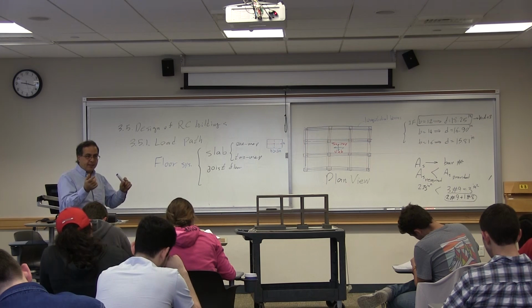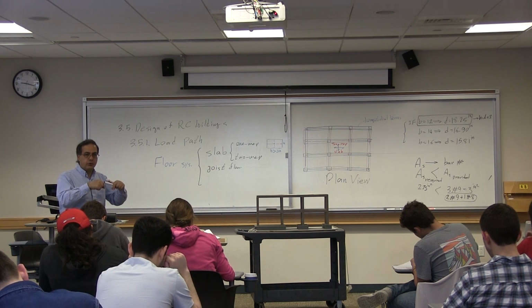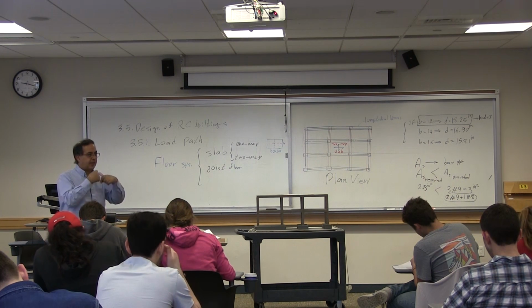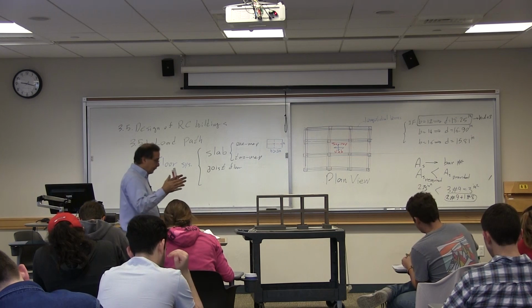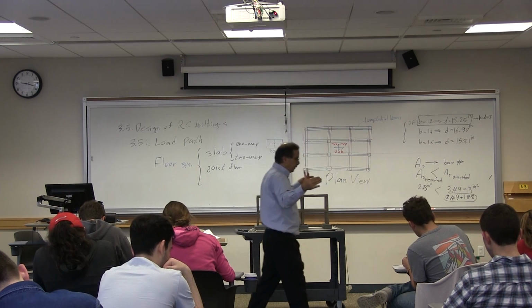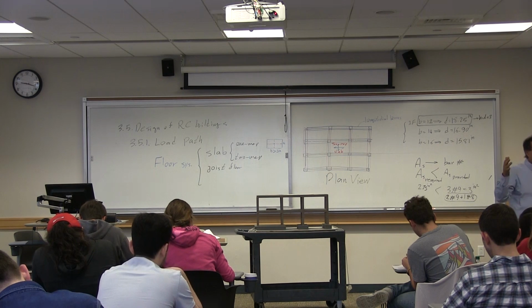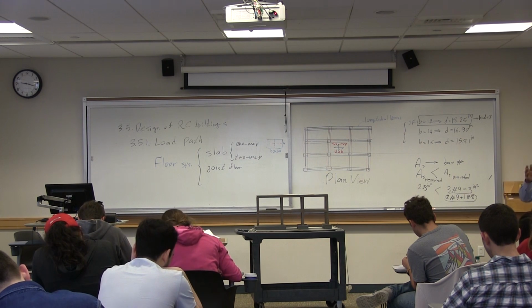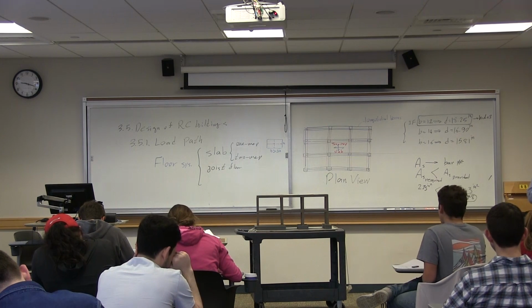However, as he said, the shorter beam needs more load to deflect the same amount that the longer beam would deform. If you have a short beam and a long beam and they deform the same amount, the shorter beam must have much more load. Otherwise, it would not deform the same amount.